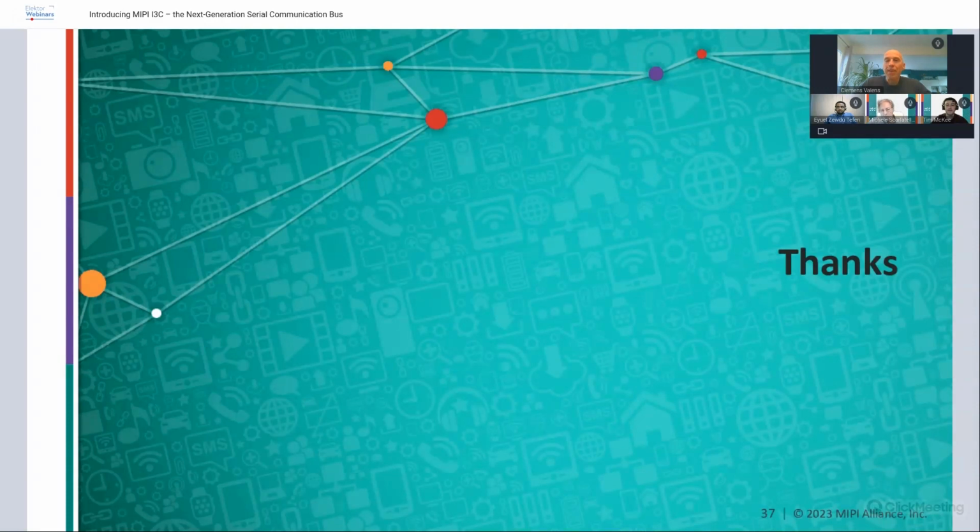It's a 7-bit address. Basically, this is dynamic addressing, so it's only happening in that system and in a certain space and time. It's not like once you assign an address to the device, it stays there forever. So it's really a dynamic address. We felt that, instead of adding an extra byte, it's probably enough for a configuration to be alive at a certain moment in time, because if you assign an address to a device, it's not blocked for the rest of its life. The addresses are reused.